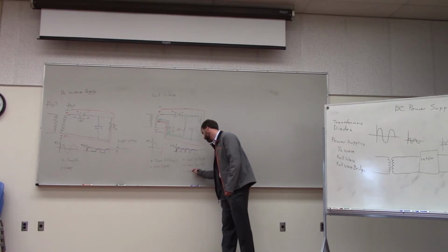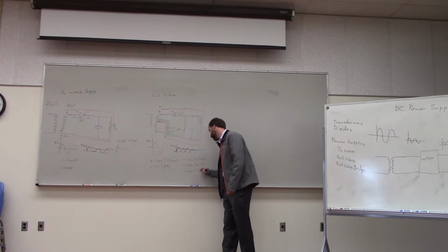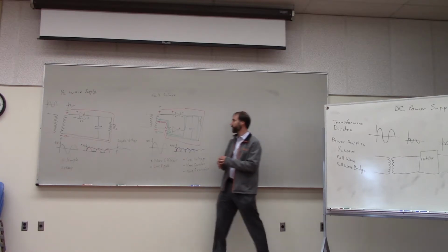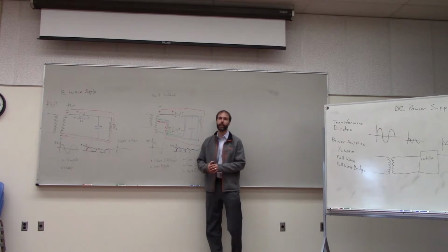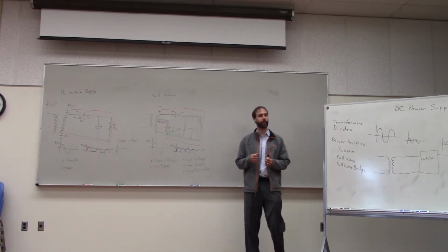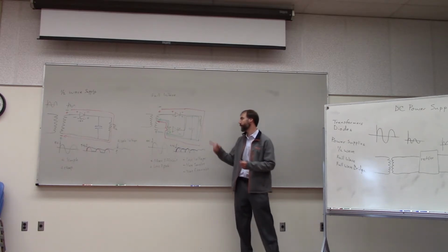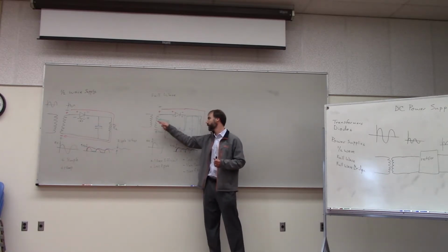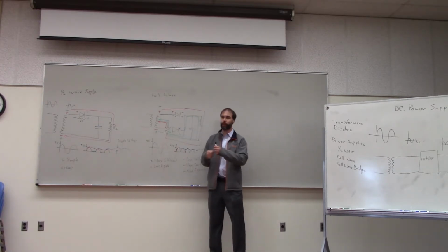And one of the things that really contributes to the expense is this CenterTap transformer itself. Okay? Turns out it's kind of a hassle to make CenterTap transformers because you have to wind them up, and then you have to go in and you have to sort of scratch the insulation off the middle, and you have to solder something on.